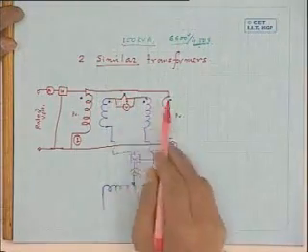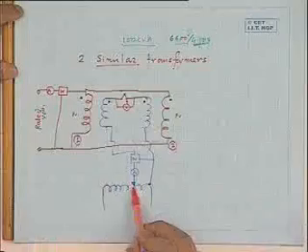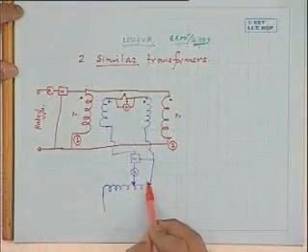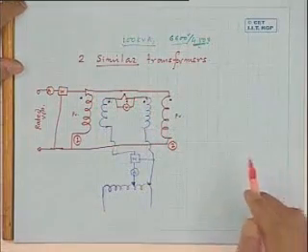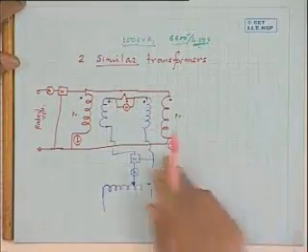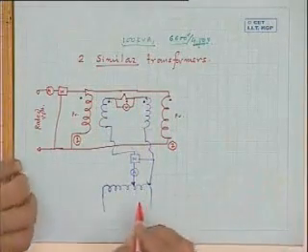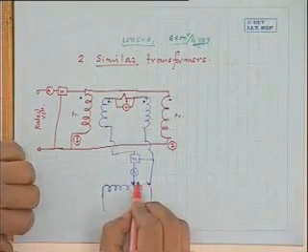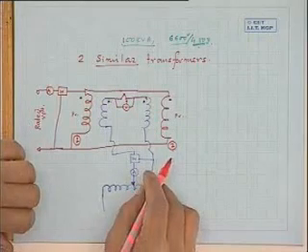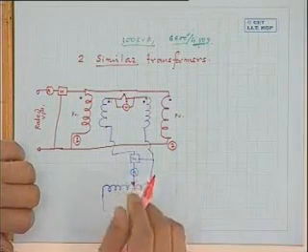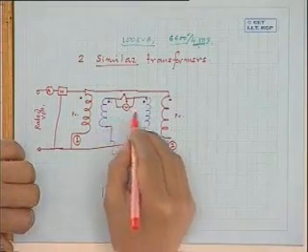Now after that, you short this out. If you short, how much will be the current on the secondary side? 0, because suppose initially this jockey is here, so no resultant voltage will act in this closed path. These 2 voltages will be in opposition. Now what you can do is slightly apply some voltage from this second source. You slowly increase this variac.